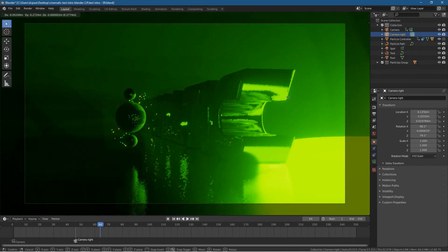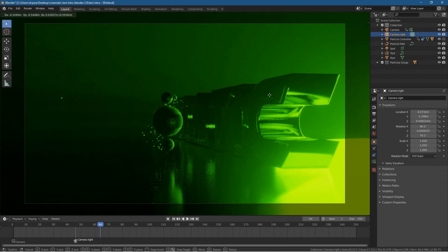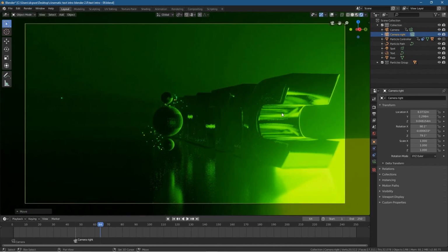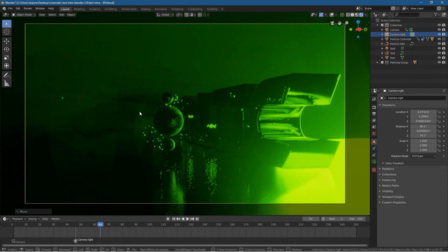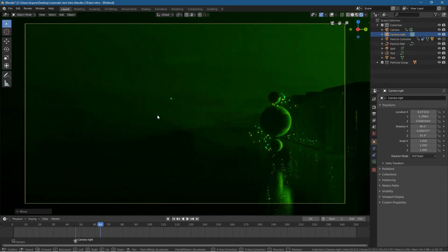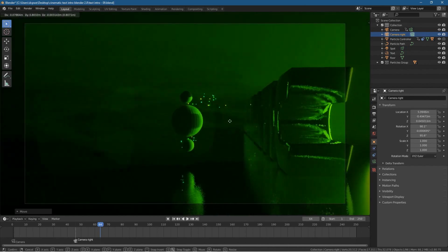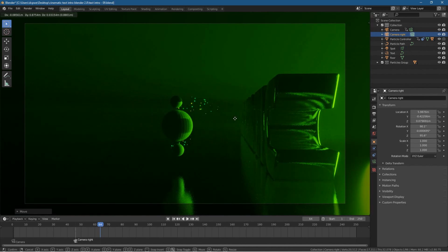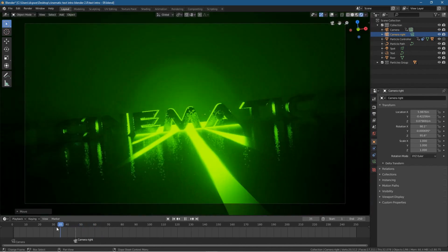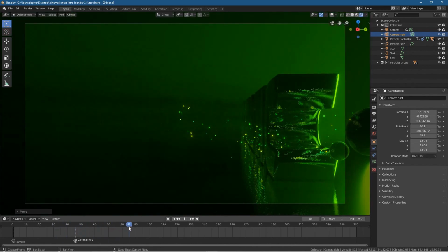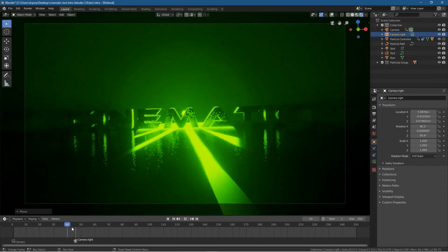So what I'm going to do is actually grab the camera and move it towards here. Let's press Shift and F and rotate it more around this direction, more to this angle. Then press G to grab it and just move it. I want to move it to like here. So we might have to move the camera back a little bit. Let's see. I think that's okay.